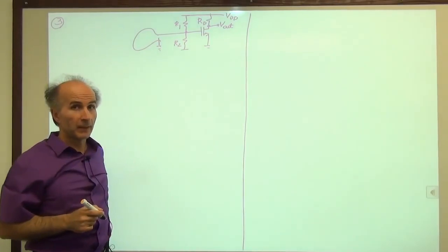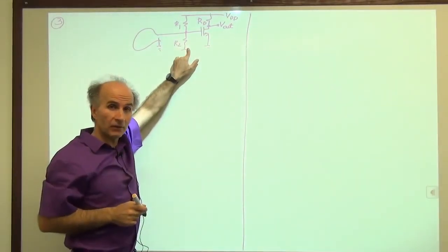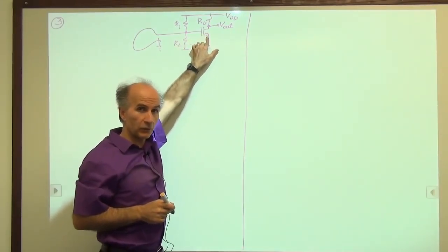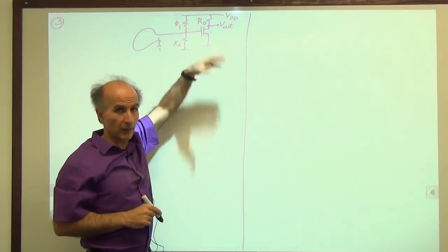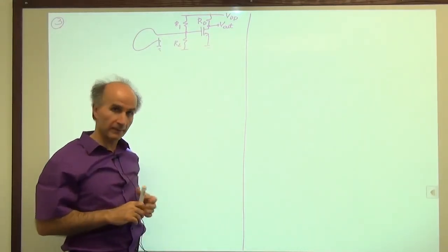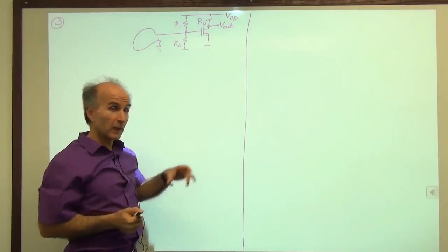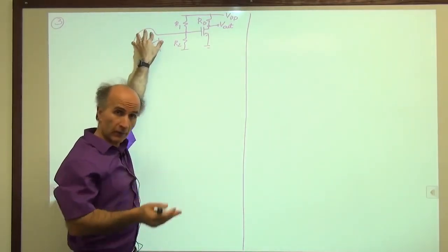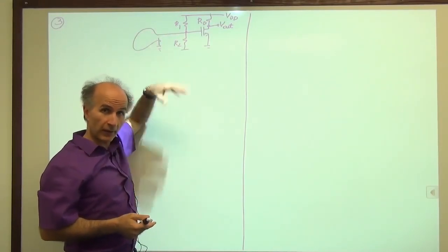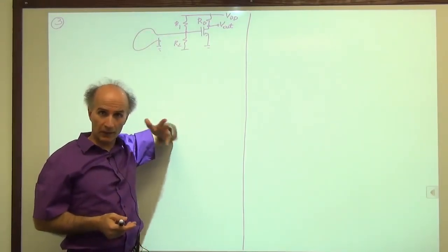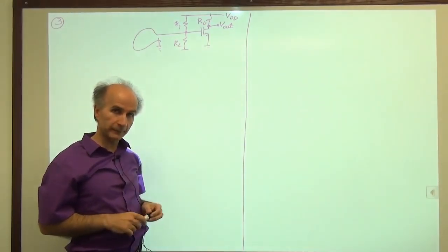And now we have a problem, because obviously this voltage is now 0, not V0, the voltage necessary to keep the transistor on and healthy. So the device is off, the circuit's dead, hopeless. So what do we do in that situation? If whatever we're connecting here, a microphone, an antenna, any other device, wants to short this to 0 at DC, meaning without any signals, then it kills the bias of the circuit.